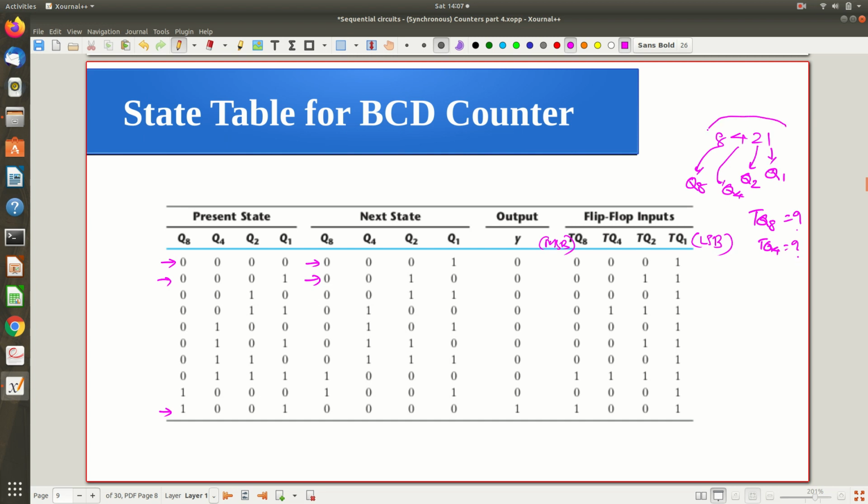Now what is this 8421 code? Hope you remember this, because in a combination, each bit position has some weight like this, right? Suppose I want to express something like 5. What is 5? 5 is 4 plus 1. So for bit position 8 there is no weight, the 4 weight should be present, for bit position 2 there is no weight, and for bit position 1 there is weight. So accordingly 5 can be represented like this in BCD. This is a convention, the 8421 code. There are many such codes, and BCD is one code which is popularly known as the 8421 code. So accordingly the bit positions are given names.